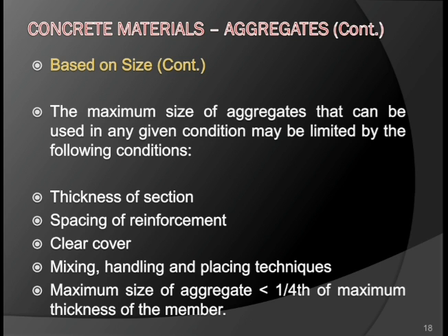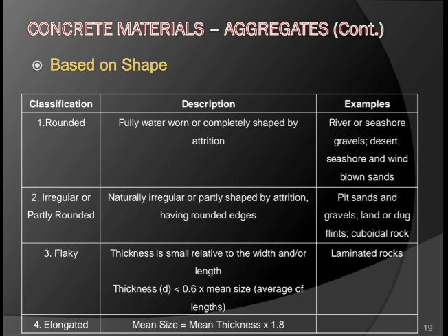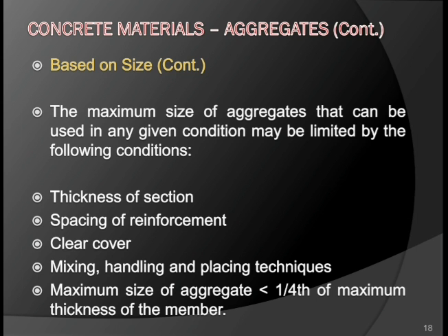Clear cover can also help in size selection. Mixing, handling and placing technique, whether hand mixing or machine mixing, conventional method or machine, and the location of the component also affect the selection. The criterion is that the maximum size of aggregate should be less than 1/4 of the maximum thickness of the member. So, based on size: fine and coarse aggregate.